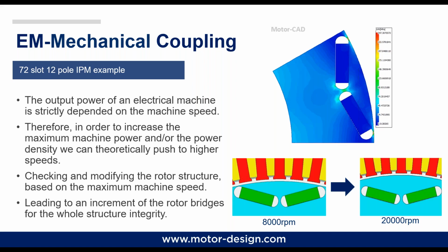And this is basically what I'm trying to do here. I want to push the machine to the limit. What I'm going to do is increase the speed of the machine and, accordingly, increase the rotor bridges thickness in order not to exceed pretty much 300 megapascal on the bridges.